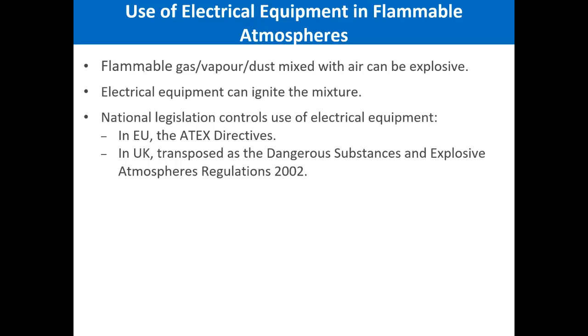Okay, so you need to make sure that you try to dilute the air and provide proper ventilation to prevent the accumulation of flammable gases and dust mixture. See, if you have only fuel gases, if you have a gas, it will not catch fire on its own unless there is a flammable mixture.